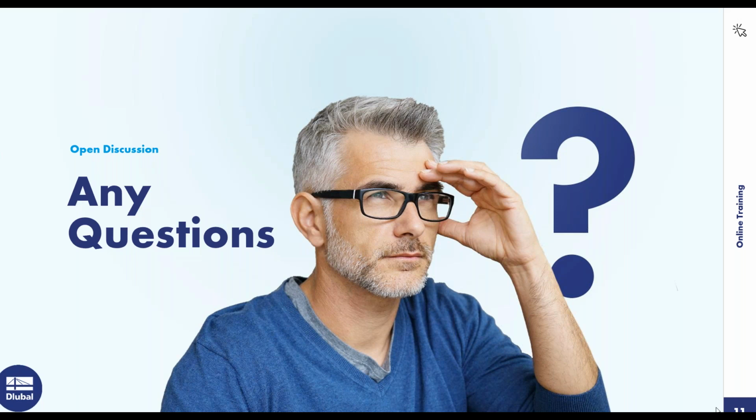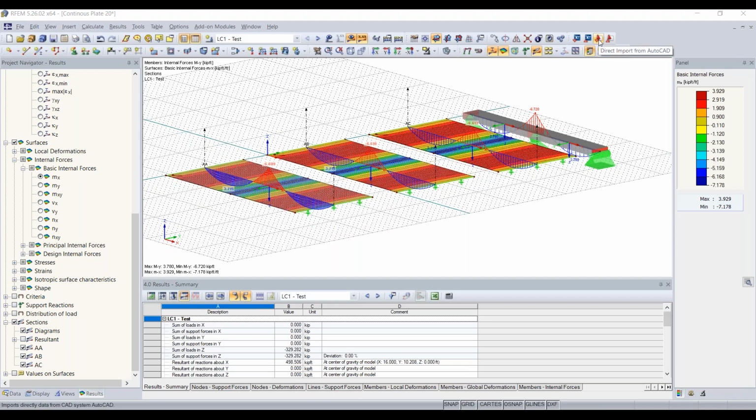Yeah, so AutoCAD is great for importing and exporting between RFEM and AutoCAD. If I hop back to RFEM, up here in this toolbar we have some direct import options. So you can directly import from AutoCAD and directly export to AutoCAD.